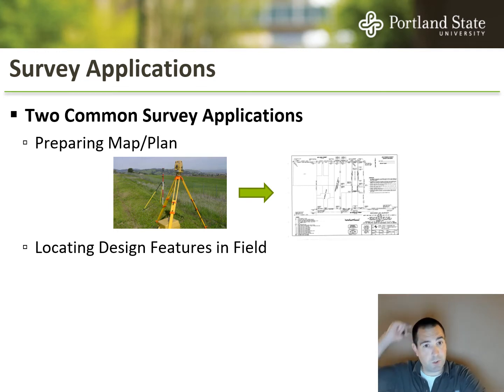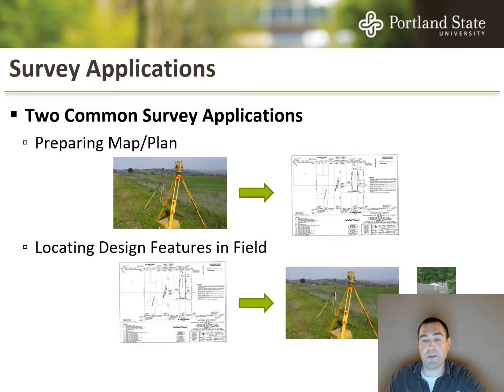Where is the corner of that building that you want built? They need to go out there, they'll put grade stakes in for changing the geometry of the surface of the lot. They'll also put in stakes so that you know where the corner of the footings are. It gets pretty detailed, but surveyors are involved at both sides of the project at the get-go so that we know what the existing conditions are, and then on the back end so that the contractor knows where to actually build things. And during construction as well too.